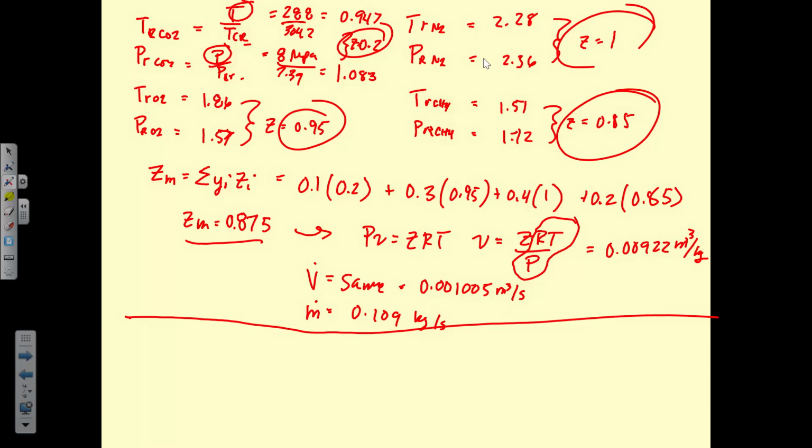Dalton's is always that second part, right? No, this is the compressibility factor. Dalton's law allows us to assume that we can use these temperature and pressure to find some conglomerate temperature and pressure. Okay, so now we're going to use Kay's rule, which is a little bit easier